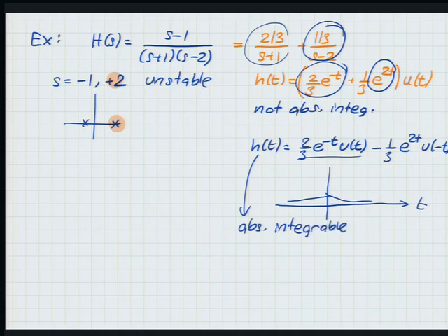But it's not causal, and therefore this is not an option for us, right? That's what's in the proof. So we assume causality because all these other options go away. They are not consistent, so absolute integrability, combined with causality, is what forces the poles to be on the left-hand side for stability.